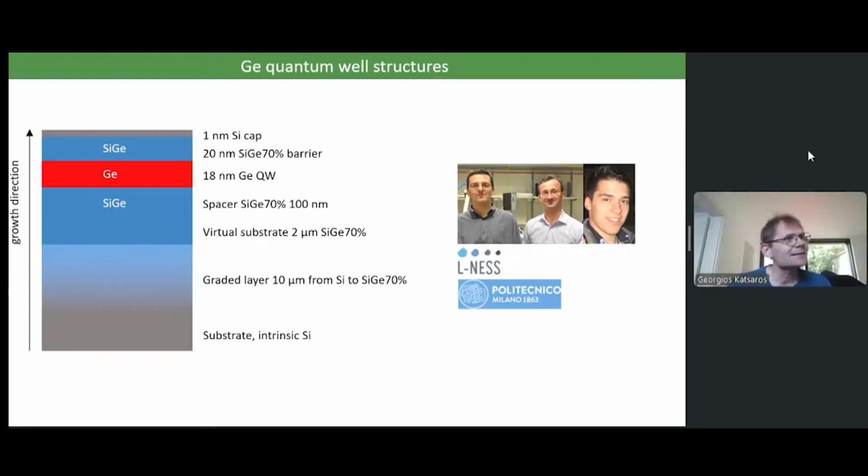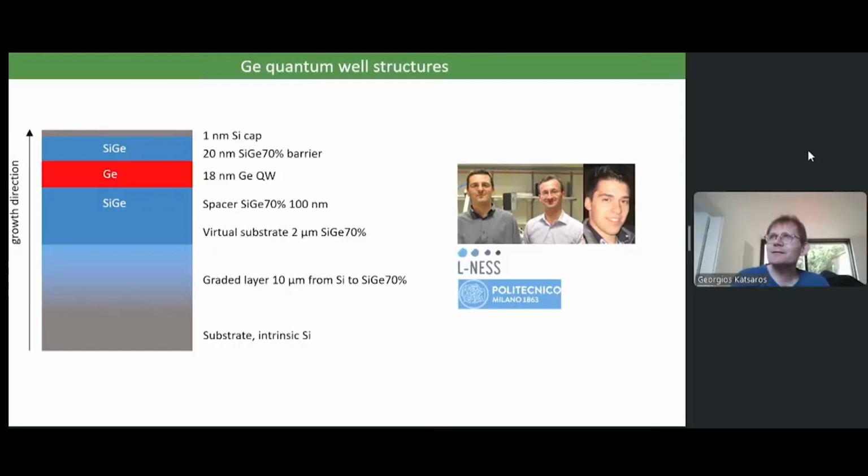And in the early days, I did an experiment. I did a Hall bar structure just out of our material. I measured the square resistance, and then I just deposited aluminum oxide on top, and the resistance dropped by a factor of 4. Aluminum oxide is known to have fixed negative charges, which for holes means it's like you apply a constant electric field. That's right. Which is a bad thing for silicon, but I guess for holes it really helps. So for many experiments, the fact that our heterostructures are on is nice because it makes life easier. Absolutely. Yeah.